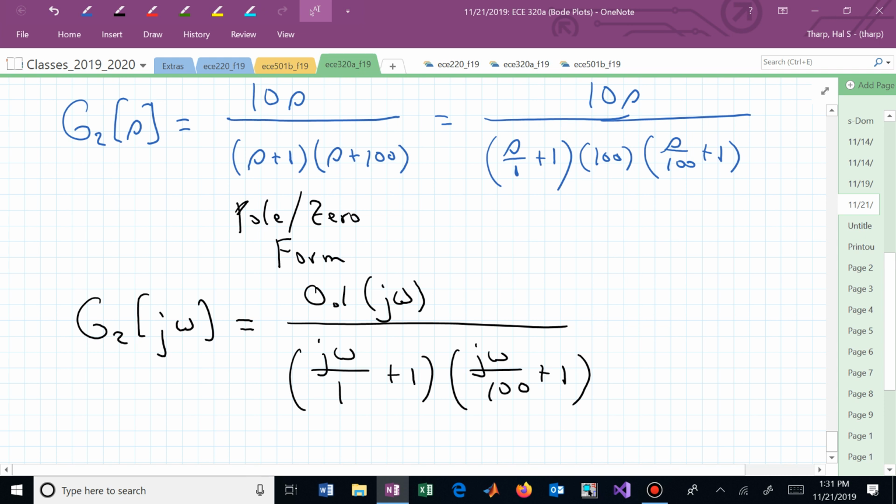90, -90, -90, -90. And now they give you a Bode plot. Your friend hands you a Bode plot, and that Bode plot at high frequencies was 0 degrees. And you go back, figure it out. You did something wrong. How'd you know? Why? You can explain, right? You said, well, I looked at your phase plot, and it was not giving me -90 degrees at large frequencies, so I knew something was wrong.